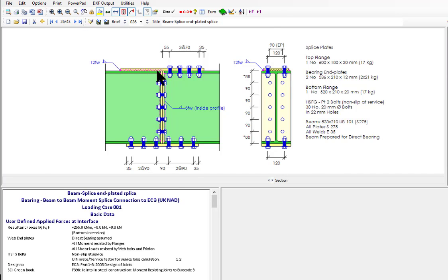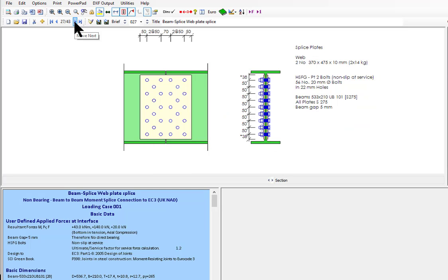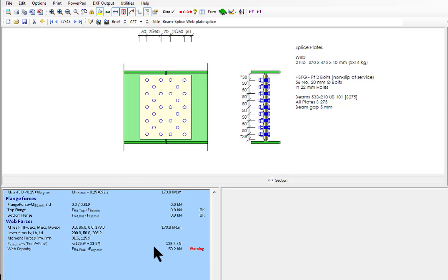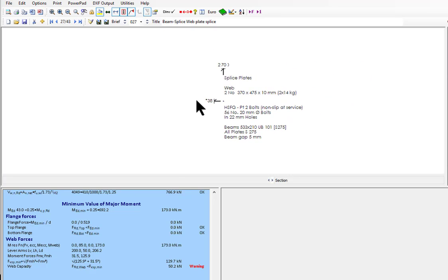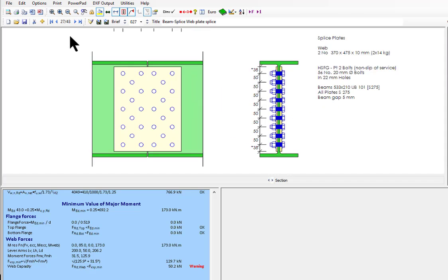And that's one with a part weld to ease fabric erection, where you can weld one side, and frequently you'll even weld one side in the bottom, and it's got an end plate here again for ease of erection rather than a web plate, all with the one configuration. And while you can do this connection, to the Eurocode this isn't very happy, and the very simple answer is it insists on there being a 25% moment capacity in the section, and it cannot resist 25% of its moment just with the web plates. So we'll not worry about that one too much.